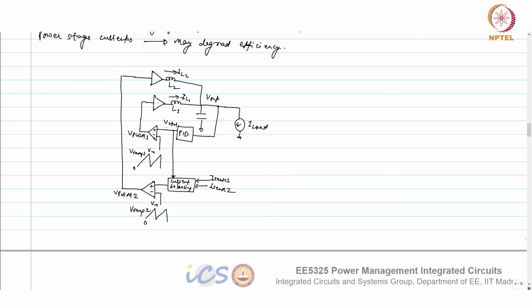So in that case, what we do, instead of running the VCO, let's say I want 10 megahertz, I will run my VCO at 50 megahertz and then divide it by 5. So again I will get 10 megahertz, but since they are divided, overclock and then divide, all the phases will be perfectly matched. So you won't have any mismatch problem.